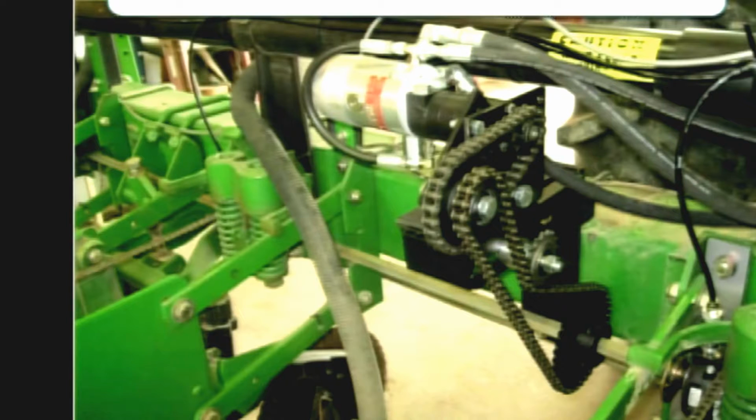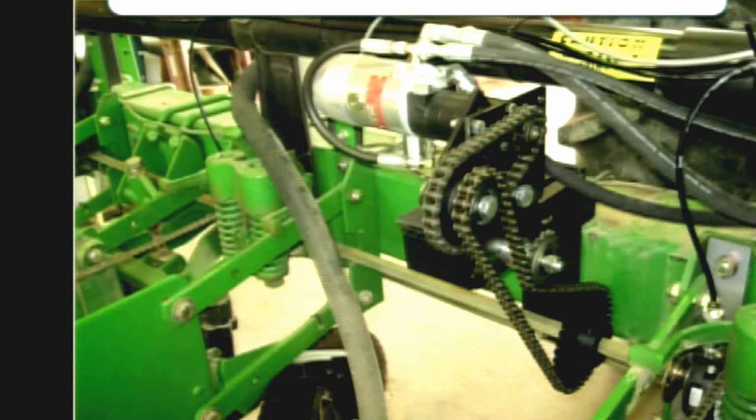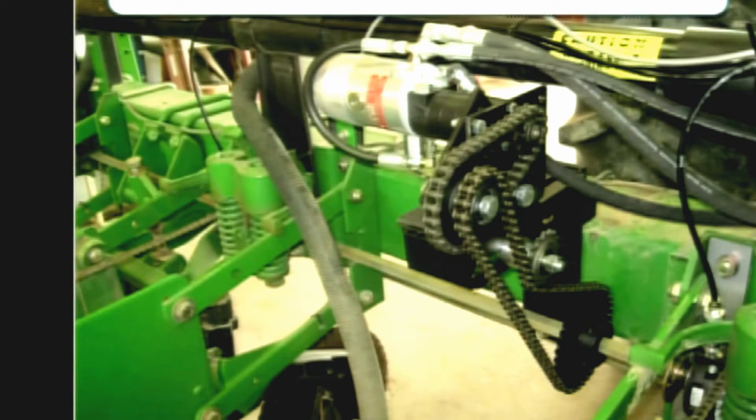So that's all we're doing. We're taking that mechanical drive that has a bunch of gears, throwing the hydraulic drive in. You got to have the display. Typically, what we call an electronic control unit will sit between this, just a box that has your wiring harness plugged into it, and that electronic control unit communicates between the display and a hydraulic motor to drive what the exact rate is that you want to put out.